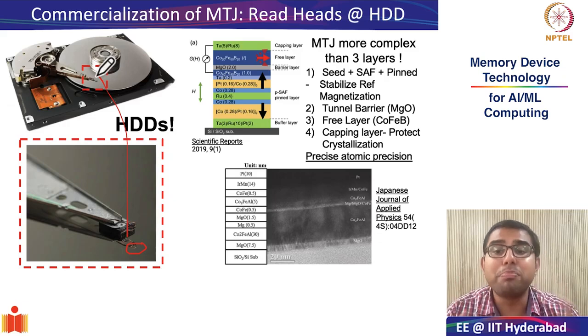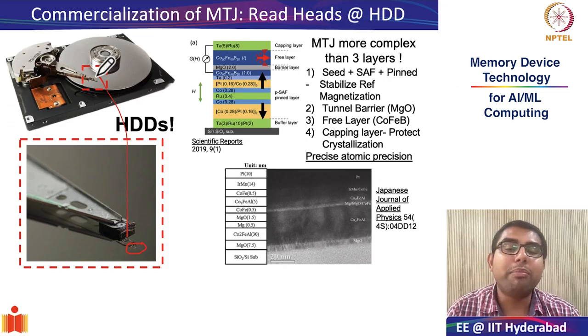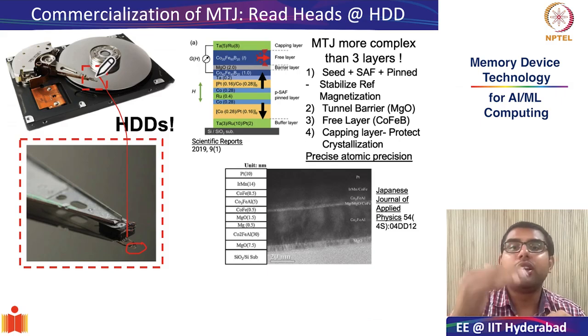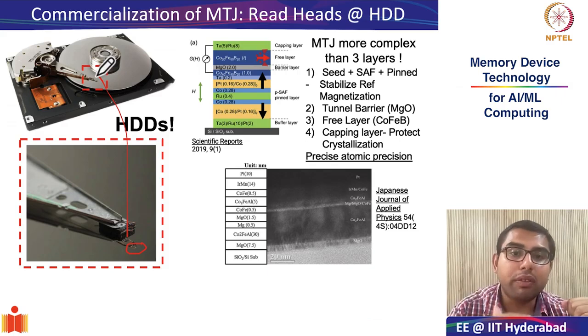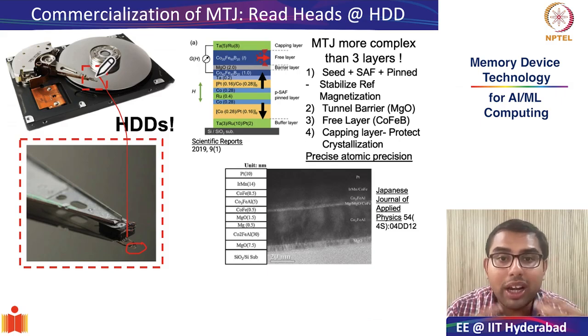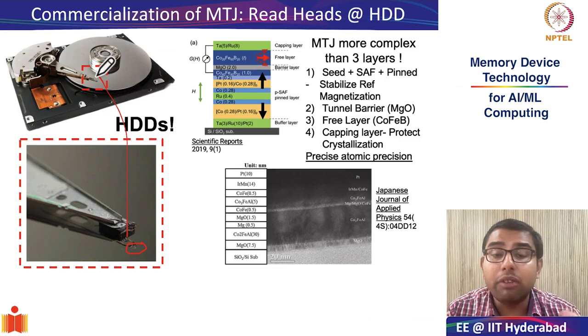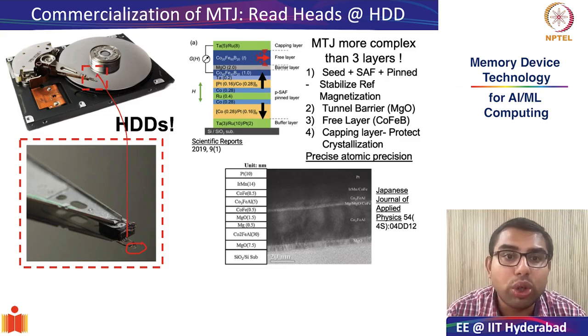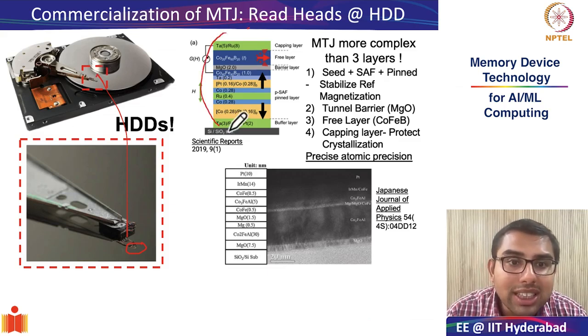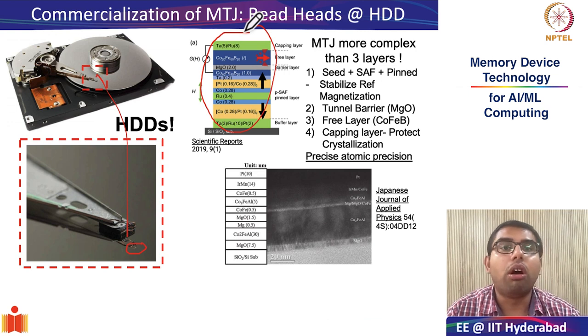However, it is very important to note right at the beginning that unlike what we had conceptually seen, where an MTJ consists of three functional layers: the fixed layer, the tunneling oxide, and the free layer, actual MTJs are much more complex. The number of physical layers in an MTJ is sometimes even greater than 40. So you see here one of these diagrams of a magnetic tunnel junction.